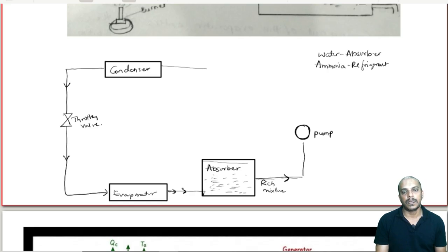So, obviously, what should be received by the condenser is this. The condenser should receive a gas or a vapor, only refrigerant we should get here, vapor which is at high pressure. That is what the compressor was doing, right. High pressure vapor should be entering the condenser, then it liquefies it, but pressure will be high here, but throttling does the remaining process, dropping the pressure and giving you the evaporation process. Now, the pump should increase the pressure, okay.